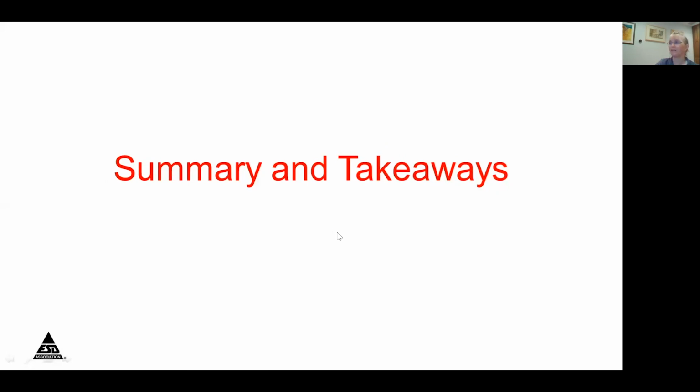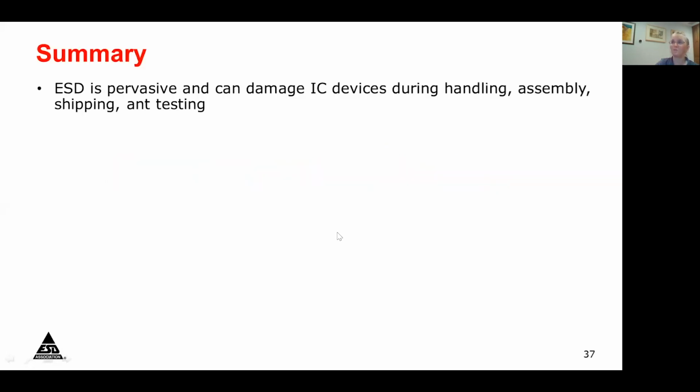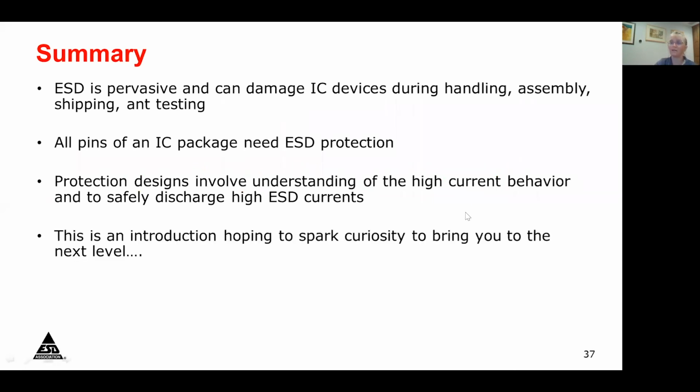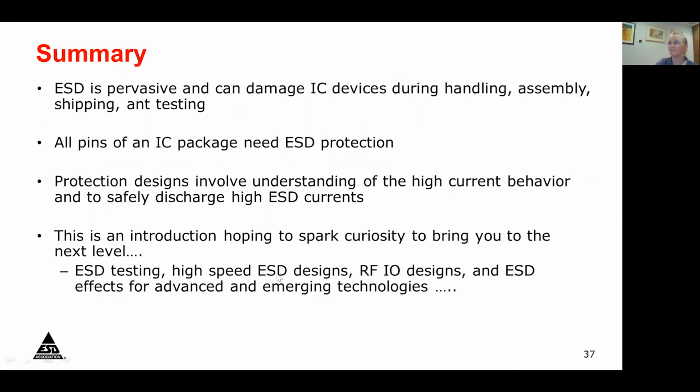So in summary, and just a takeaway, I hope I've highlighted to you that ESD is pervasive and can damage ICs if not properly controlled. All pins on an IC need protection. And protection involves understanding of the higher current behavior in order to safely discharge. So this is an introduction. I'm hoping, over lunch, to spark curiosity and bring you to the next level of understanding with this.